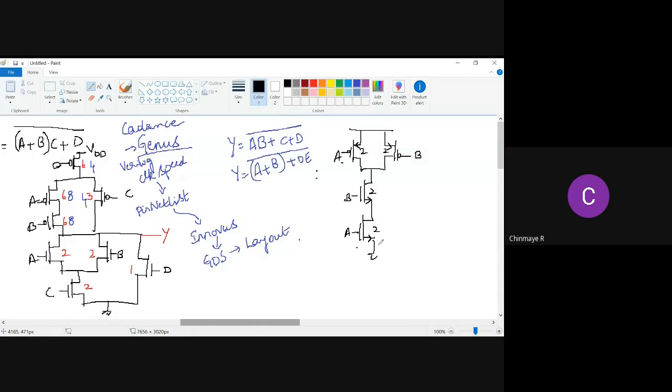Now you have a source capacitor here, which is equal to 2C, correct? Because its width is 2, we just approximate all the capacitances, that is the capacitors at gate, drain and source, as 2C, right? So what do you think is the capacitor here?